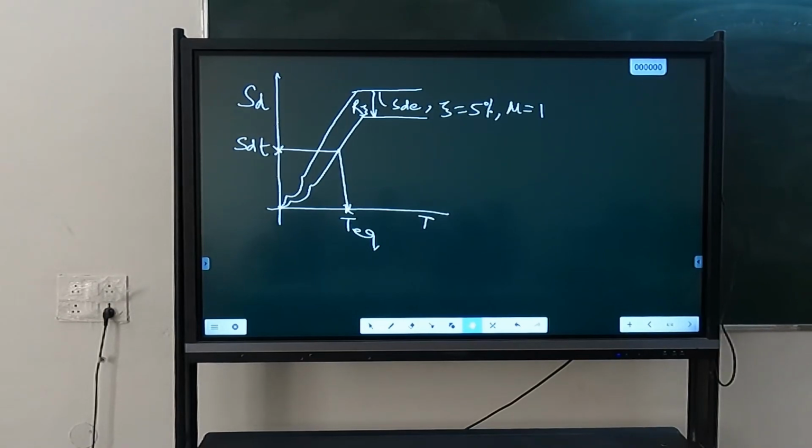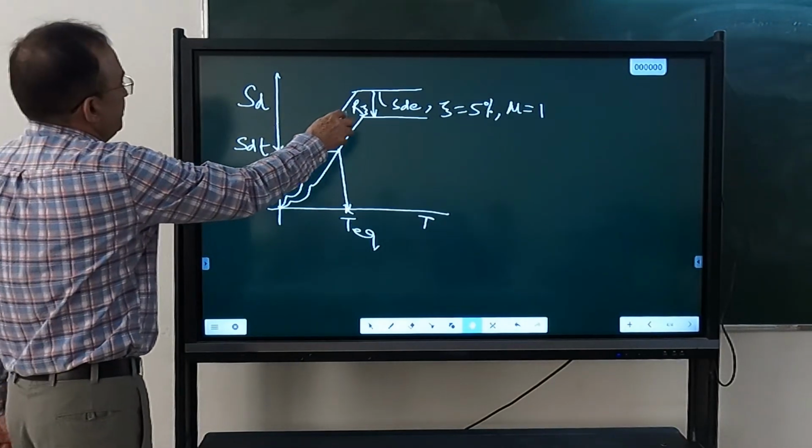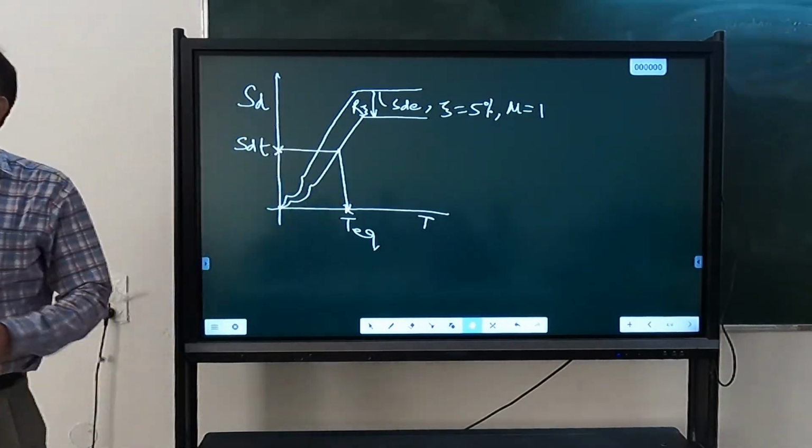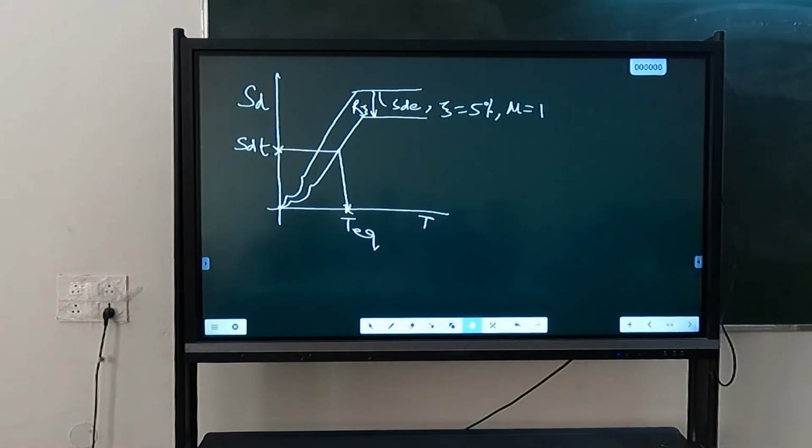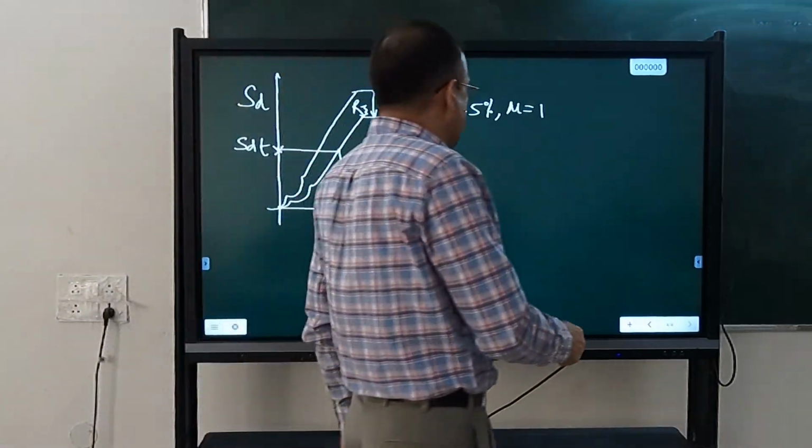Right. From that capacity we have to match with that displacement. For reading the response spectrum, we have to convert this into equivalent single degree freedom system. So wherever we will be reading response spectrum, it is a must to convert that into equivalent single degree freedom system. That's why we are converting it into equivalent. Once we know T, then we can calculate K equivalent. Now we can calculate the base shear of the original building.